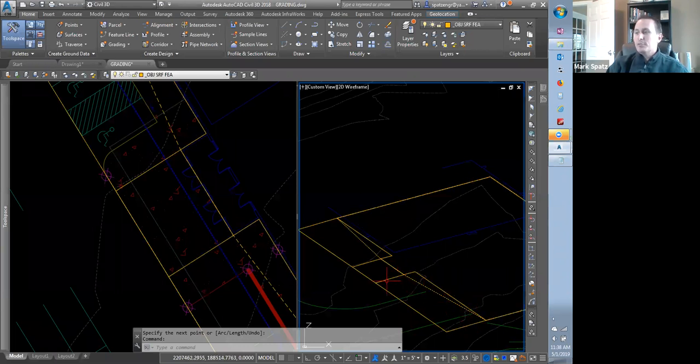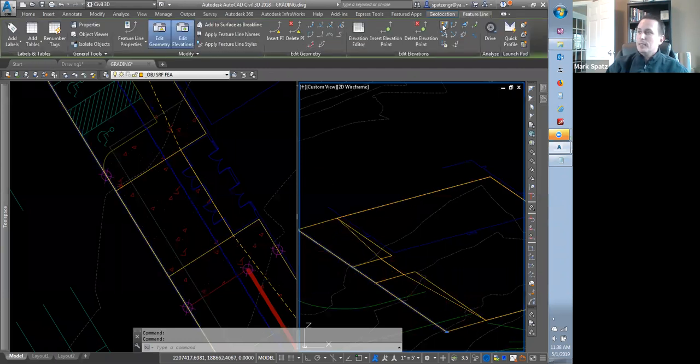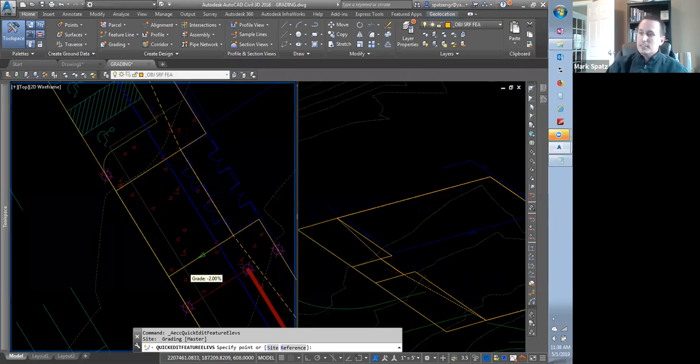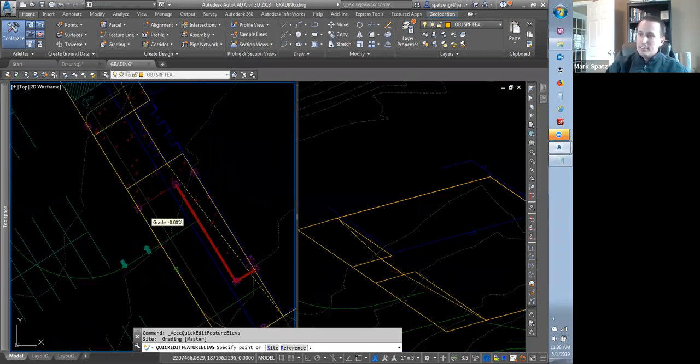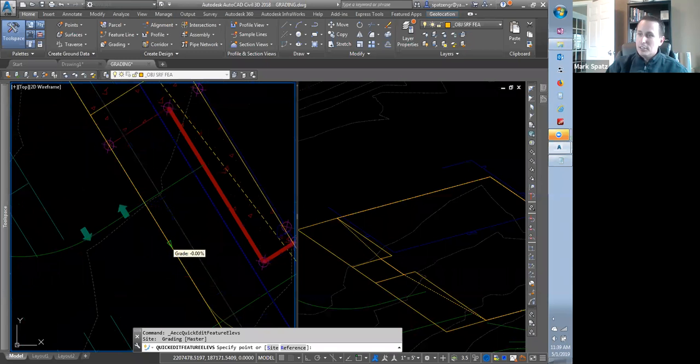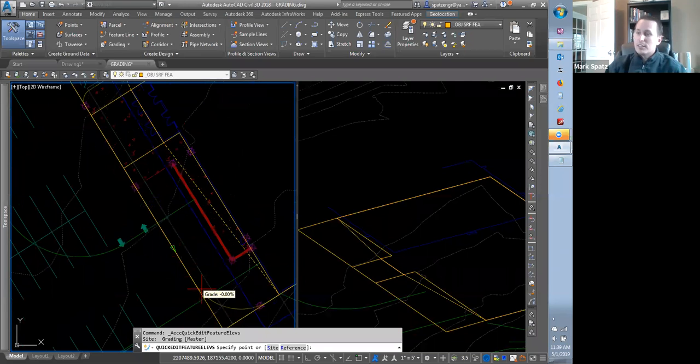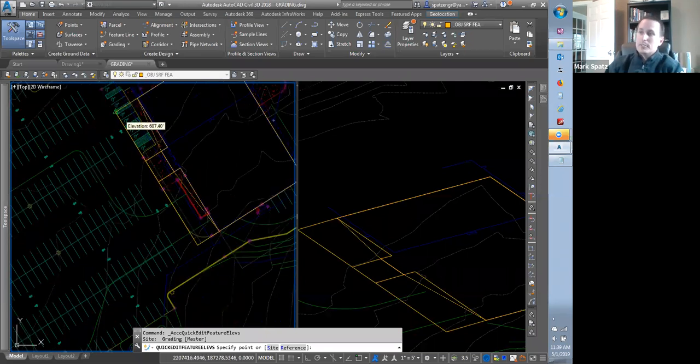You can see, because that's a slope change. But essentially now we have 2%, 2%, and this feature line is adjusted. If we click onto that feature line, we can see these percentages. Like you can see, okay, now this is negative 2%, that's negative 2%, 0 across. And this is actually such a low slope, from here down to here, it's so long that slope is actually beyond the third decimal place in the percent. So that's looking pretty good. So that's what we're going to go with.